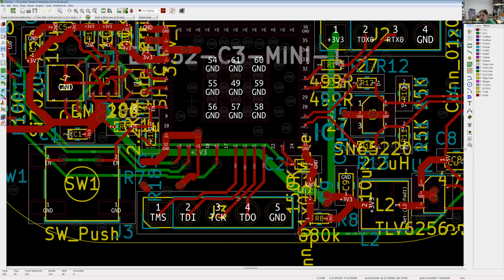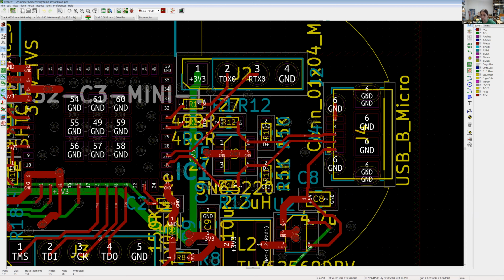And I probably need to remove these until I get the actual version that can use it, because I think the USB standard puts 3 volts or 5 volts on the D+ D- line, and I think these are 3 volt. I think these are 5 volt tolerant on the ESP32, but it's not always the best idea, and it can't be used anyways. So until I can get a version of this module that can handle the I/O from the USB, it doesn't really do me any good. And so then I've got the TX/RX lines for communicating, debugging, and programming.